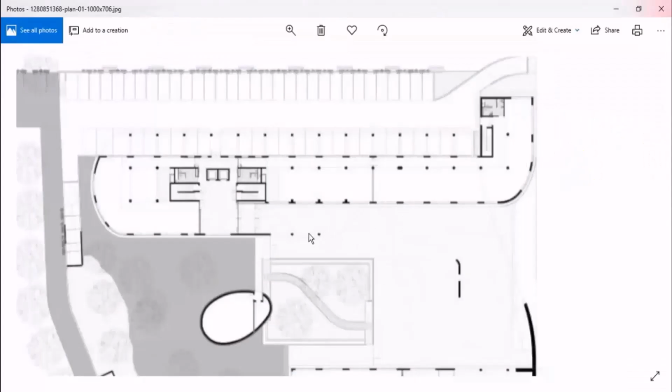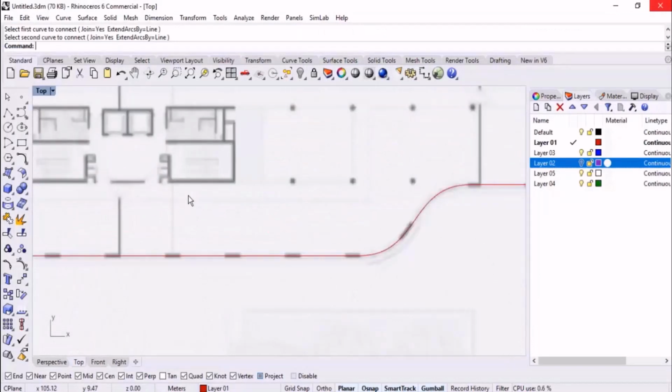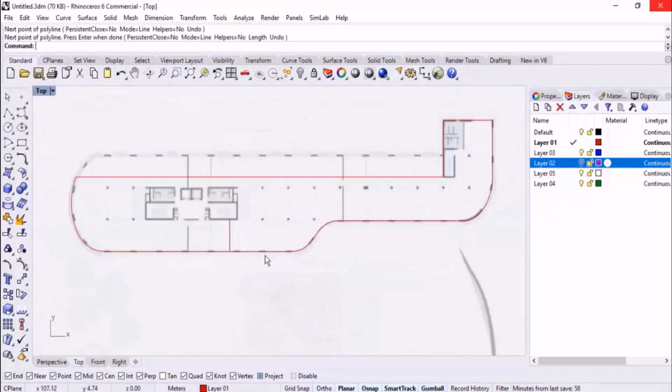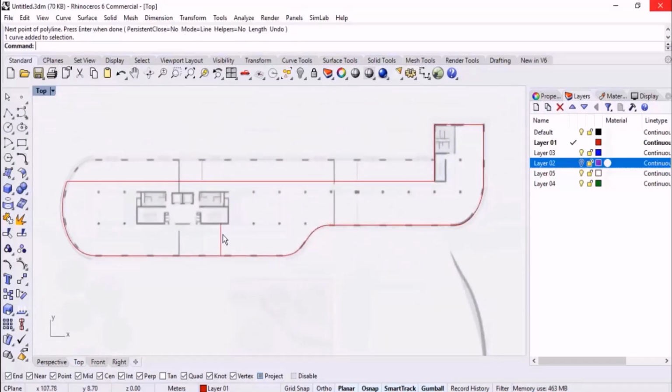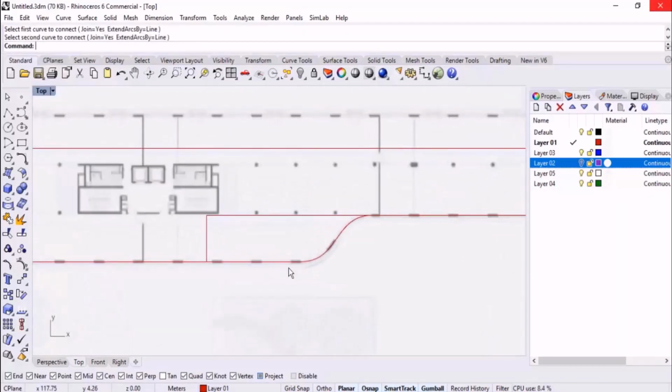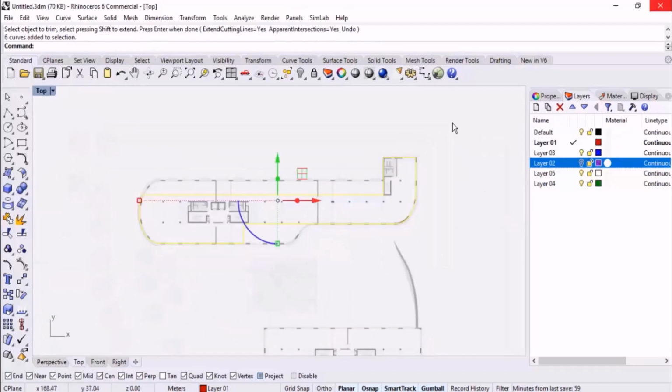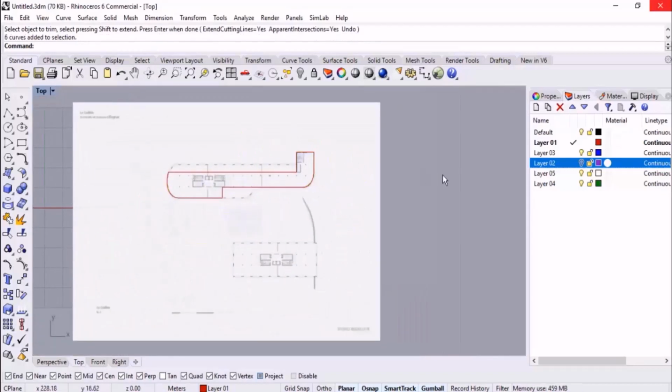But what about the bottom part? Let's check it out. Here from the end of the stairs, as you can see, we have a straight line. Again, back to Rhino, I pick the polyline. Let me specify the position that I want to sketch. I sketch the perpendicular line. Then I need to connect these two lines with each other. CON, connect. Check this out, by this way, and then I trim the extra parts like this. Well done. So layer 1 is completed and type 1 is done.